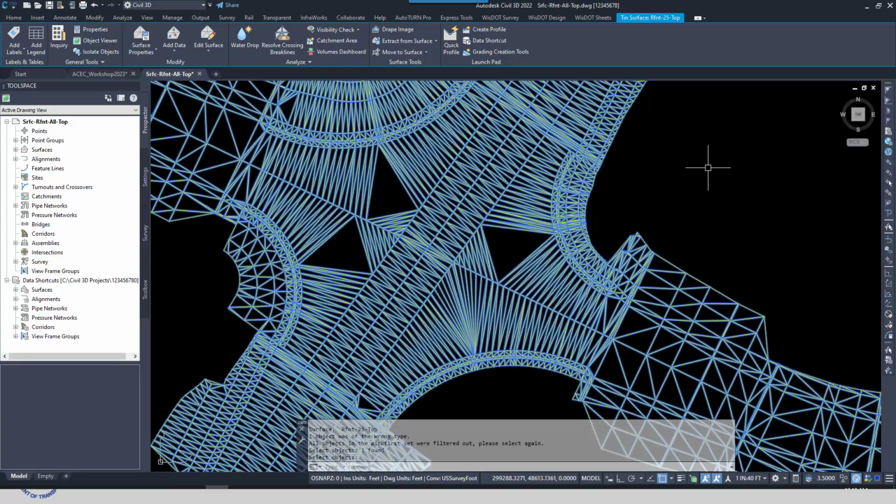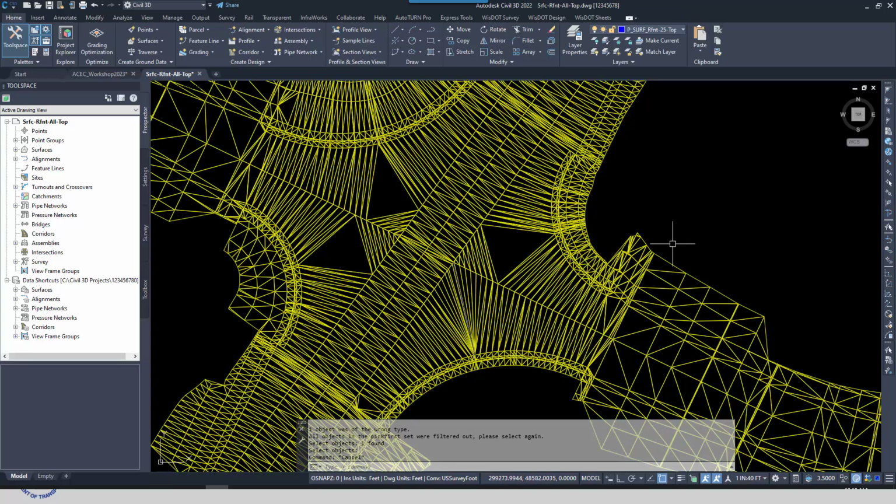And it's a good way to do things too, because now when we extract our break lines, that one line that we've added is going to be included in that break line set for the contractors. So that'll assure that when they build a surface, the tin edges are going to be oriented the way they should be in the intersection. So that's sort of the manual way to do it. Let's go ahead and undo that.